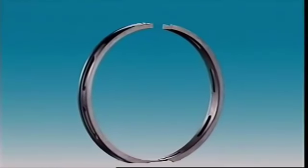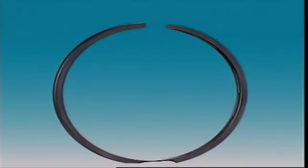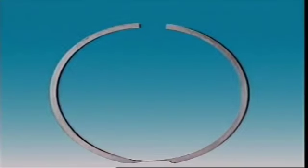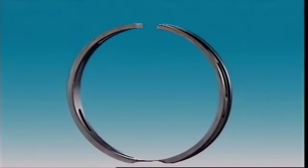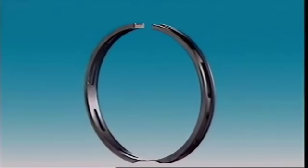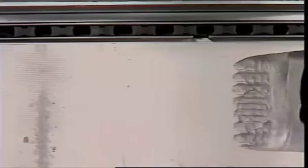Oil control rings prevent excessive oil working up into the combustion chambers. It can be a one-piece ring that depends on its own tension to hold it against the cylinder walls. Slots in the ring and holes in the piston behind the ring let oil return to the sump.